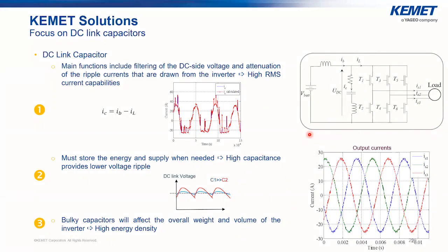So for the DC-Link, for the EDC or for the electric compressors, the selection of the correct product family and technology is really crucial to optimize and ensure that the capacitor will handle all the application conditions. The DC-Link, of course, needs to be selected to filter all the RMS current coming from the power modules and also from the battery side.